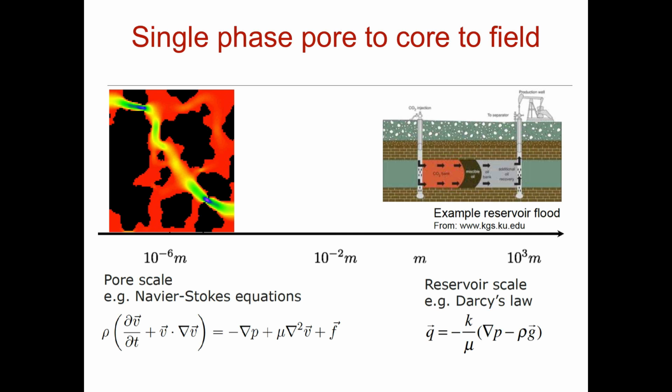And then what you will simulate on reservoir level is the variation of Darcy's law, where basically you have a gradient of generalized pressure, permeability, which is ability of the porous medium to transmit fluids, and viscosity of the fluid. So you can see a built-in assumption into this. This is a model. It's not always true. And there's a built-in assumption that permeability and viscosity of fluids are independent. They're not. So technically, the permeability that I measure depends on the fluid that I use, but we typically do corrections for that, and in any kind of modeling, we assume that they can be decoupled. Okay. So those are simplifying assumptions.